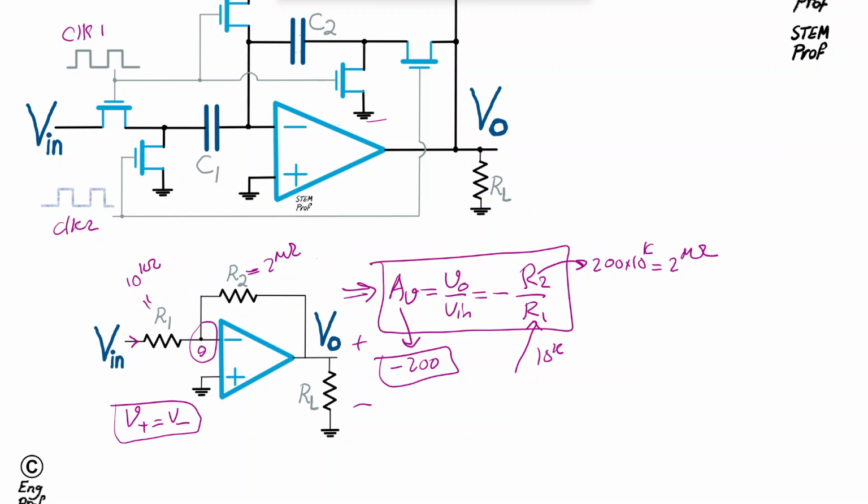So effectively what I'm trying to say is implementing these sizes in a chip as a resistor is prohibitively expensive, and also sort of accompanied with a lot of parasitic effects and non-idealities. So how do we avoid this while at the same time still getting a gain of, let's say, negative 200? That would be the thing that we realize using a switched capacitor circuit.